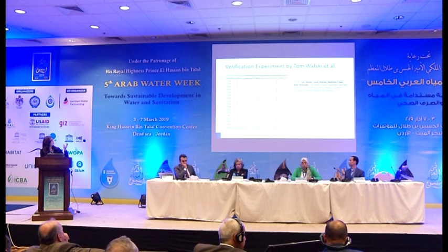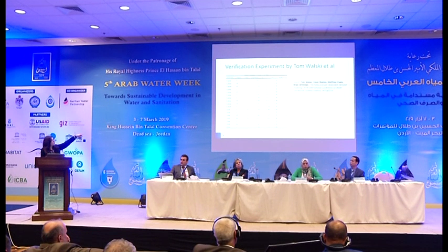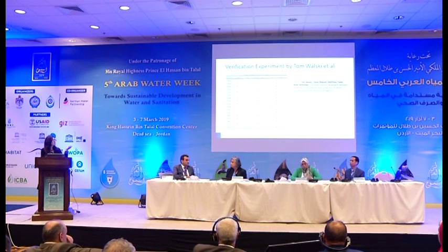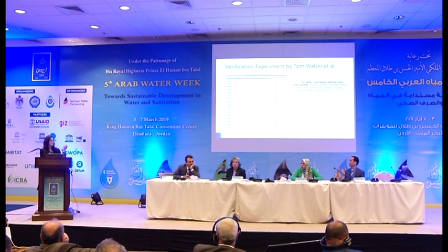So they achieved an exponent for the pressure of almost 0.5, as shown in the table: 0.51, 0.52, 0.55. So the exponential form of the pressure-dependent demand analysis, using the emitter equation Q = K multiplied by P to the power 0.5, is in good agreement with the experimental results achieved through the model produced in the lab.